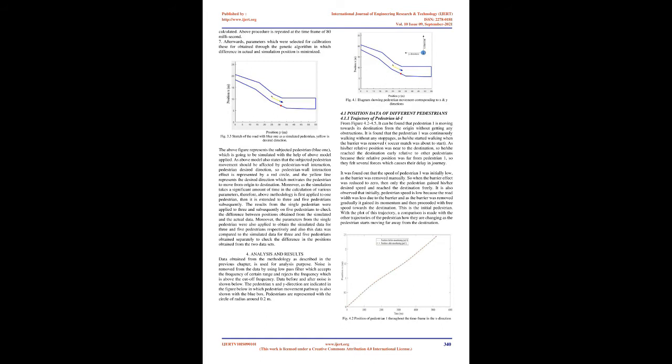Centrifugal forces between pedestrians. Effect of borders and obstacles. Relaxation time. Centrifugal forces between pedestrians: relative speed impacts are considered, as pedestrian speed is affected by neighboring pedestrian speed. Moreover, it is assumed that the faster preceding pedestrians will have no repulsive impacts on those behind them.